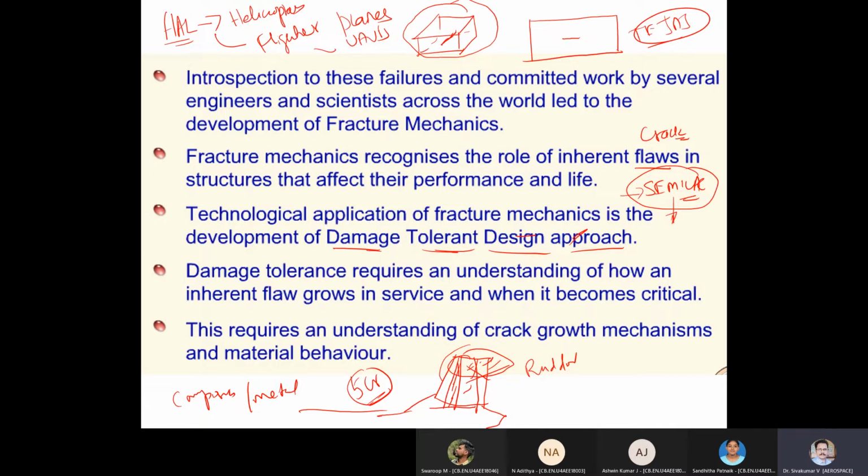Okay, they will embed the crack inside. What exactly is the crack? The one which is found using A scan, B scan, C scan. That crack they will incorporate inside the finite element analysis or other testing process. Then they will undergo the analysis. From that they will find the response of the structure, through which they will come to know whether you use the original structure or the damaged structure.